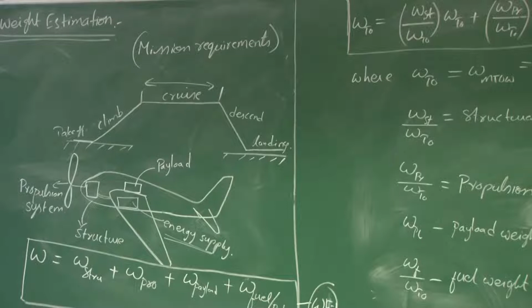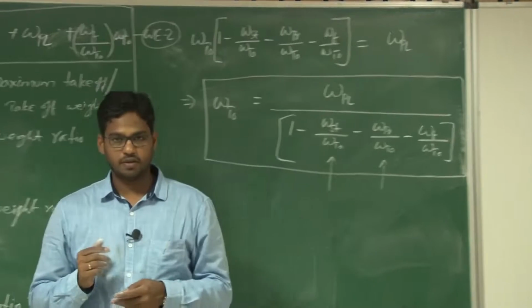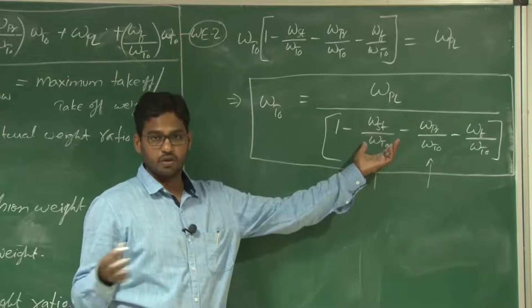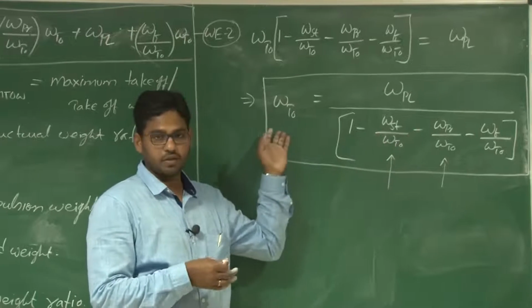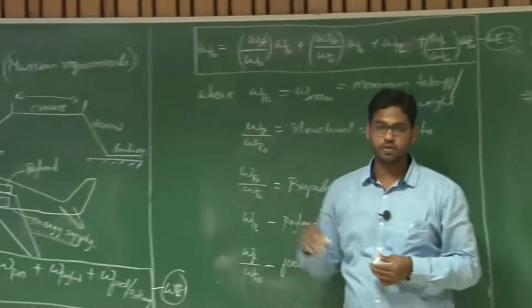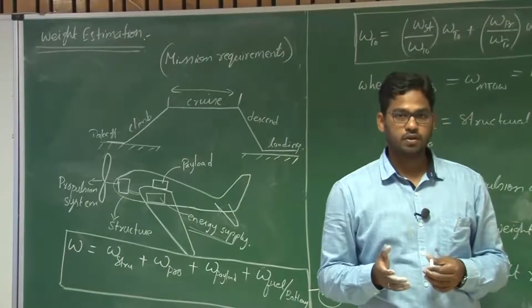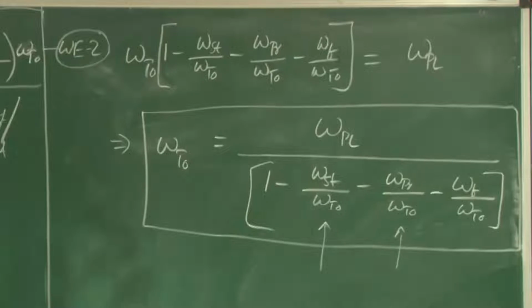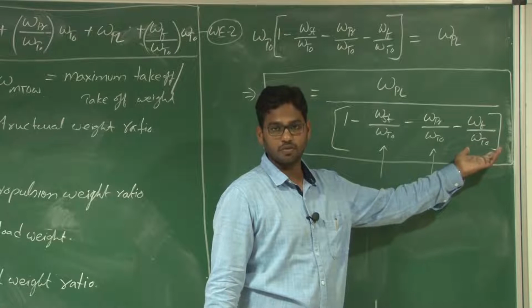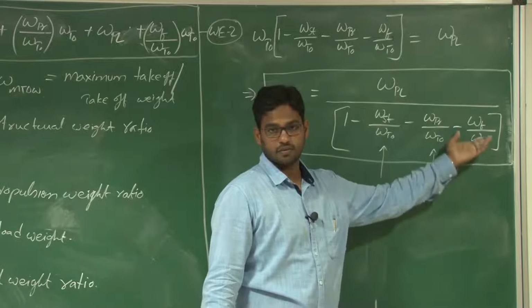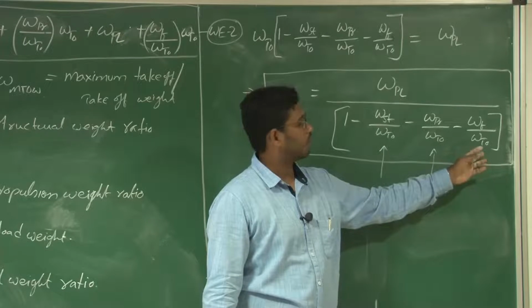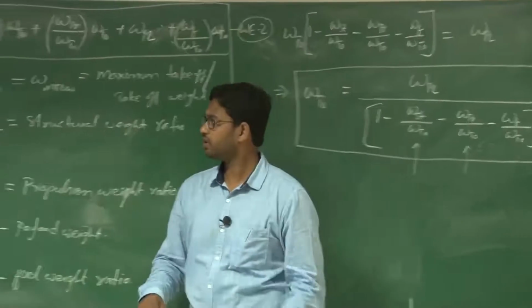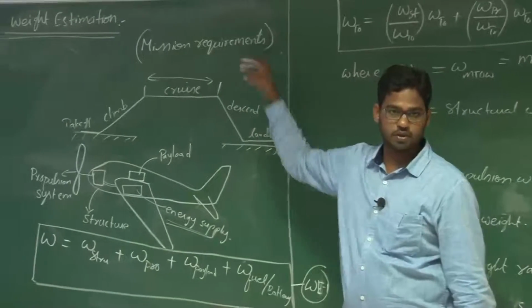Right? And then when you are trying to estimate, by considering the values of previous UAVs, what is new with this WTO? What is new with this particular UAV that you are going to design? So this fuel weight ratio will vary. If you are designing a UAV based upon an IC engine, where fuel is the energy that is supplied to the system, right? So if you are designing that UAV, this fuel consumption or ratio changes based upon your particular mission requirements, right?